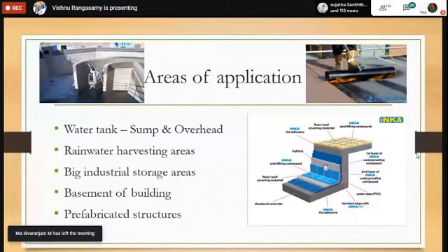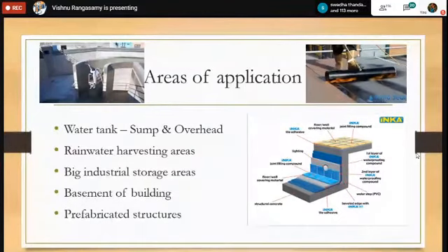So what are the layers? Like if you have concrete, you can mix a chemical for concrete. Next, crack filling. Next, you may coat a waterproofing chemical over that. You may have a bitumen sheet over that. Nowadays, most people like